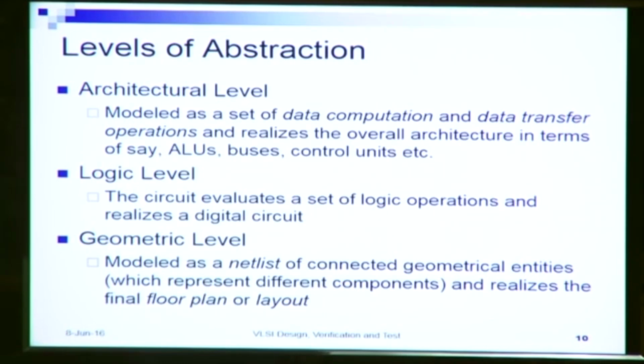At the logic level, the circuit is represented basically as a set of logic operations, or let us say a state machine with respect to a controller and a set of Boolean equations that represent the register transfers that happen. These Boolean equations and state machines together will form the behavioral description at the logic level. And what will we do in the logic level? We will realize the circuit in terms of a digital circuit, in terms of gates and flip-flops.